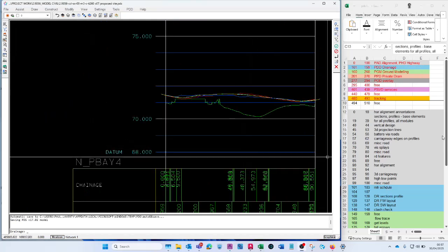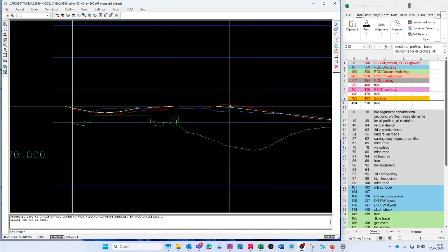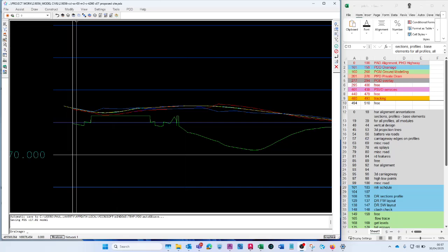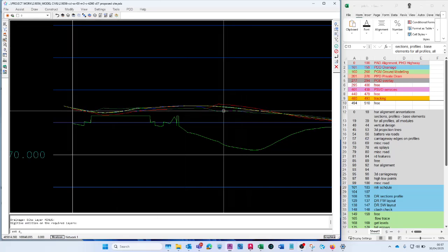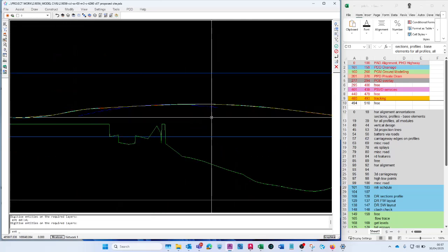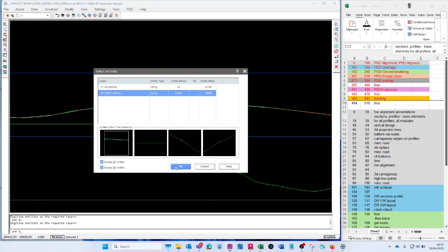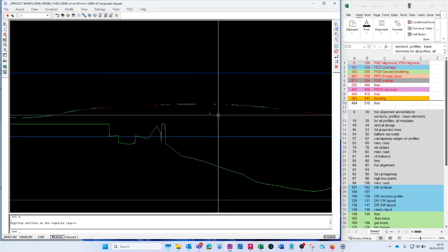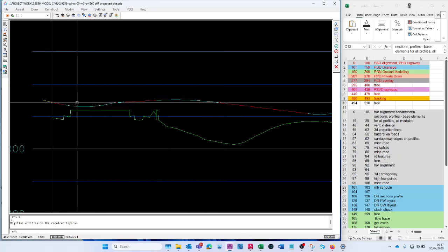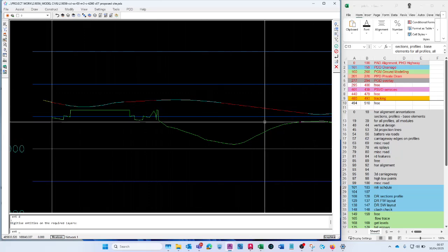Okay, so let's look at the vertical design. Now, on this, there's the vertical design and then there's the carriageway edges and center line. They're a bit different. The carriageway lines get added on and we design your carriageway. Turn this off. That is your 3D design. That is the vertical design of the road. So the red is your straights, the cyan is your curves.